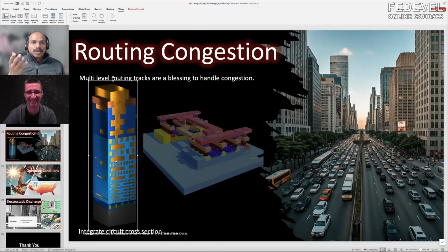Interesting. And in a PCB you can take 45 degrees? Yeah, because it's thick enough and it still has good electrical properties. Now, we do have 45-degree structures on the top metal layers, but definitely not on the lower metal layers. We only do that on the very top metal layer. Here I can very nicely see it's bigger and bigger and bigger. So the top layers will be mostly for power distribution or something.